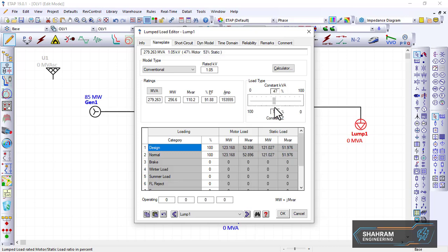And then I was still getting errors whenever I thought I would be using 50 and 50 here, 50 up and down. I noticed down here, whenever it says motor load, it goes to half, but whenever I increase, the static load disappears here in the MVA, and then it turns all to the motor load, and it keeps what I have entered purely.